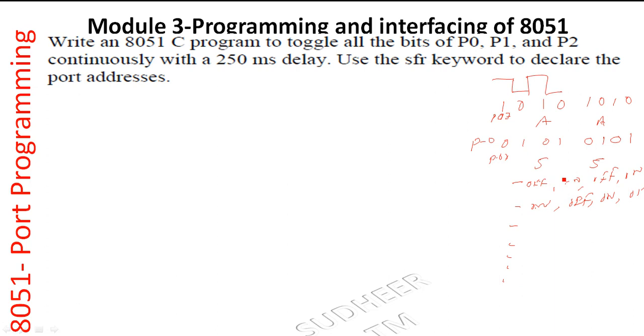Okay, so we need special cases. We need to use the SFR instead of P0, P1. We have to use SFR keywords. That's also SFR, special function register keyword, in our microcontroller.